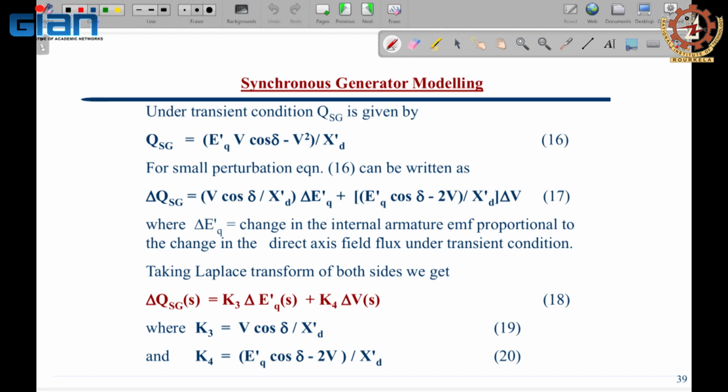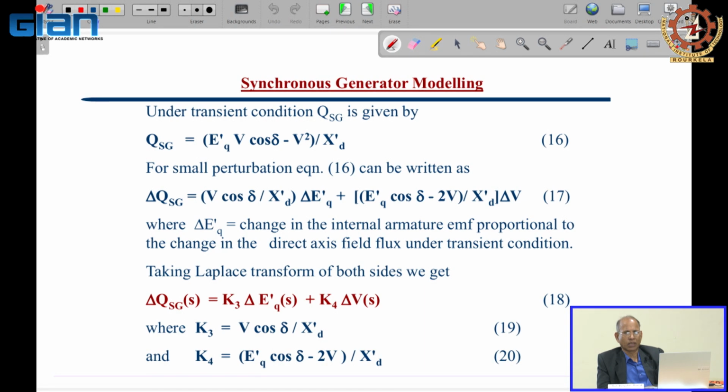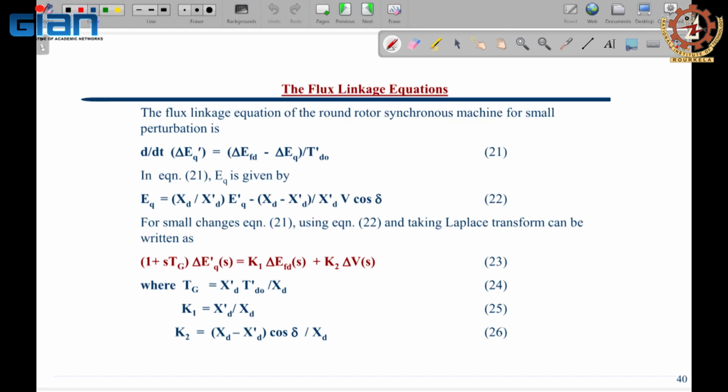Then when you are dealing with hybrid power systems, then you will have another generator like the synchronous generator attached to the diesel generator. So, you have to have the model for the synchronous generator, particularly for what study you are doing, for the load frequency or mainly reactive power control. So, you write the appropriate model for the synchronous generator. I am not going into too much detail because of the time constraint, but at least you can get some kind of feeling.